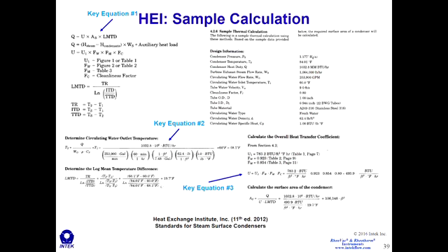The last bit that you need is these basic formulas, these key equations here. On this slide you can see a sample calculation and use this to come up with your own cleanliness factors or even evaluate. I would highly recommend evaluating your formulas, if you're using cleanliness factor now, because we found in many cases errors in these formulas in operating plants that result in a cleanliness factor that's just not useful.